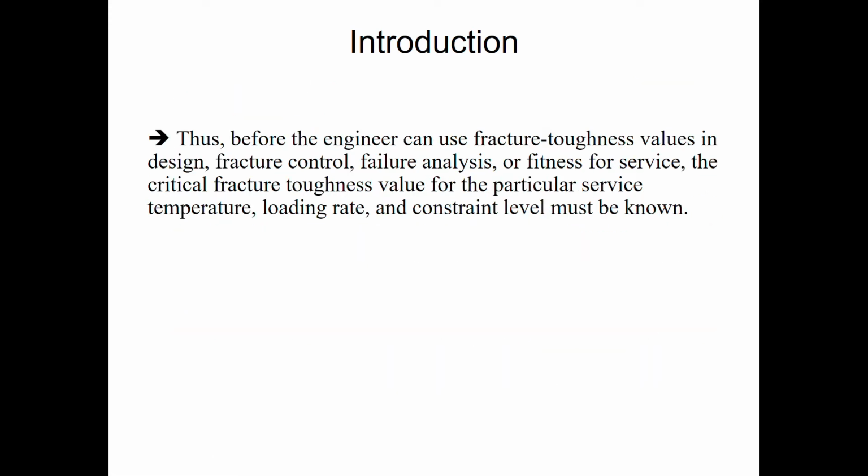Thus, before the engineer can use fracture toughness values in design, fracture control, failure analysis, or fitness for service, the critical fracture toughness value for the particular service temperature, loading rate, and constraint level must be known.